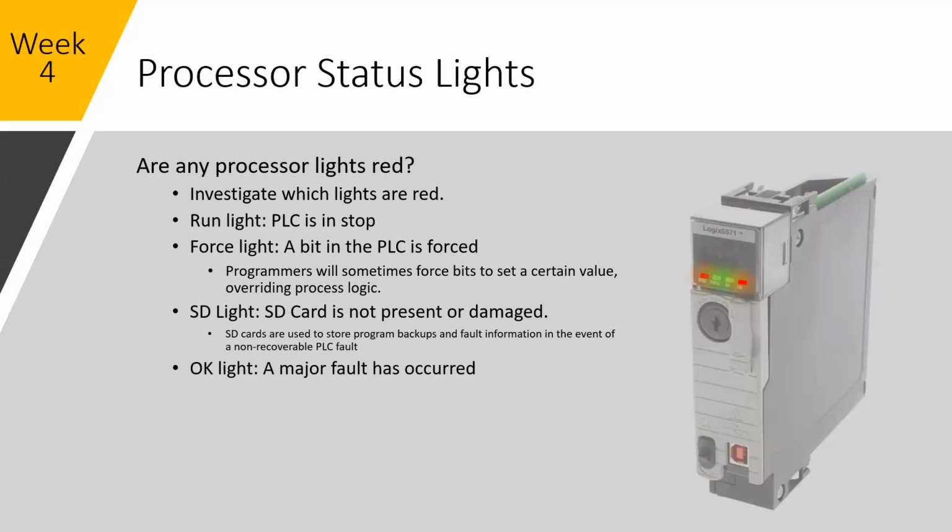Better practice would be making logic changes to prevent the code from turning things on. Forces do have to be enabled to work. If you're in there modifying code anyway, forces can be a powerful troubleshooting tool, but they can also really wreak havoc on logic if you're not careful.